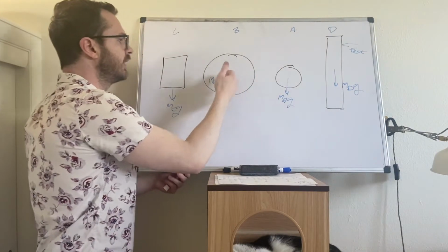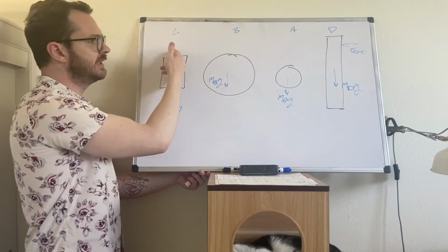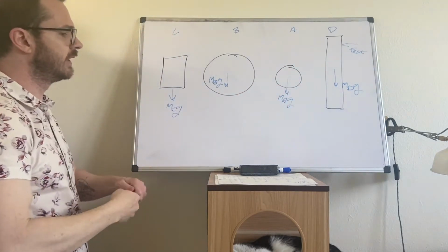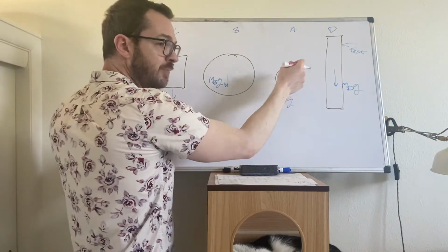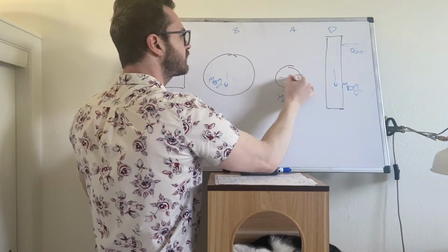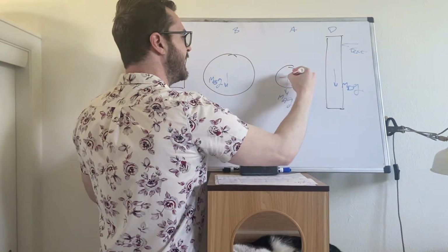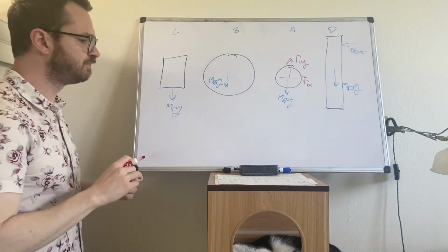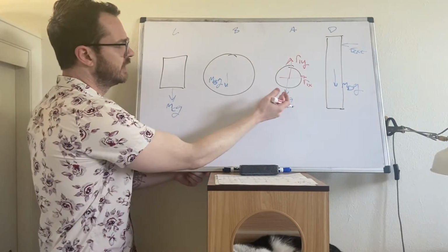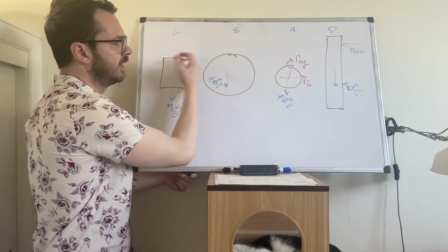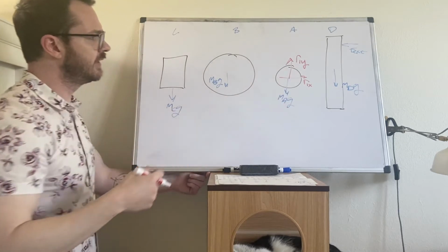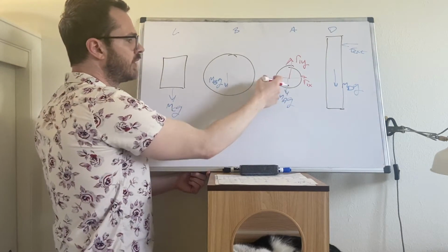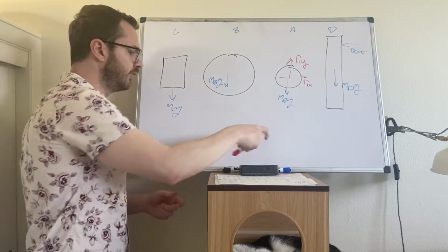There's pin joints, there's a gear interface, there's tension in a cable, there's something going on with the contact points. Okay, let's start with body A, the pin joint through the middle. This will have an X component and a Y component, so R1X, R1Y. Next, let's move through the mechanism, through the discs. We'll come back to the handbrake last. So, what is going on with the interface between the 2 gears?